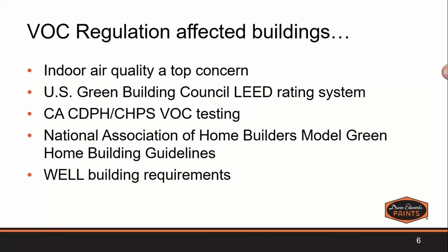And one of the requirements for LEED is that a paint needs to prove its low emitting status. On a manufacturer's end in California, this means that we have to follow the California Department of Public Health's VOC testing through standard practice. And this method is actually called the Standard Method for the Testing and Evaluation of Volatile Organic Chemical Emissions from Indoor Sources Using Environmental Chambers, which is quite a mouthful.